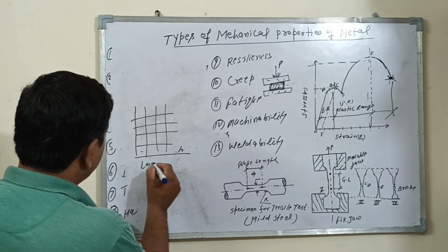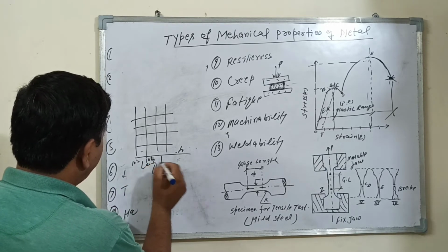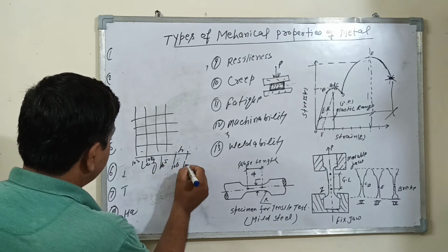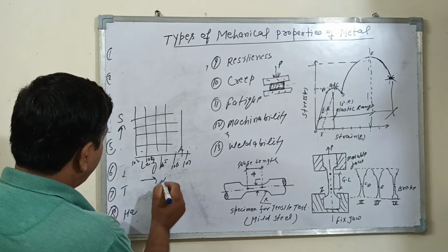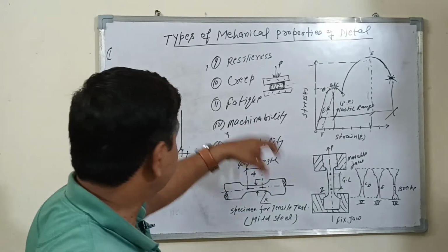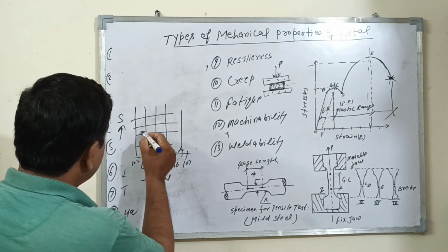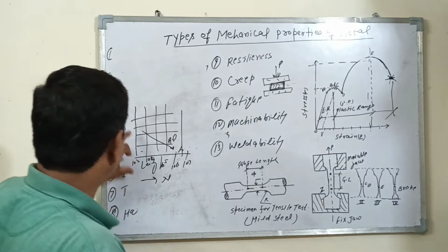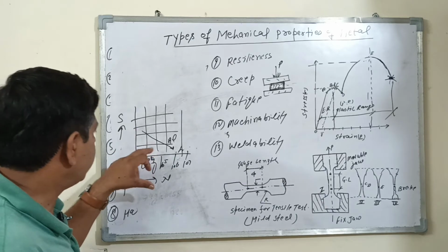The fatigue test is plotted as a log graph, with 10-3, 10-4, 10-5, 10-6, 10-7 up to this. This axis is the stress, and this is the number of cycles. If you want to check the fatigue for aluminum material, the curve is like this. For aluminum the stress is very low, the load is very low for checking aluminum.